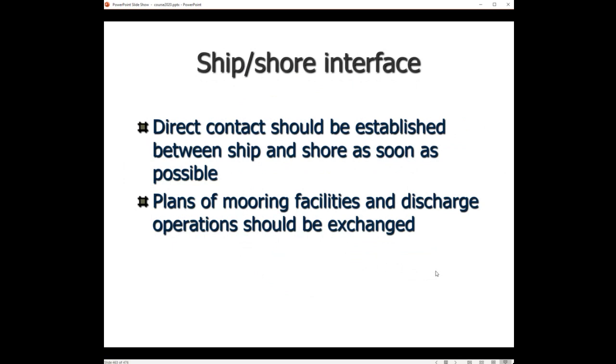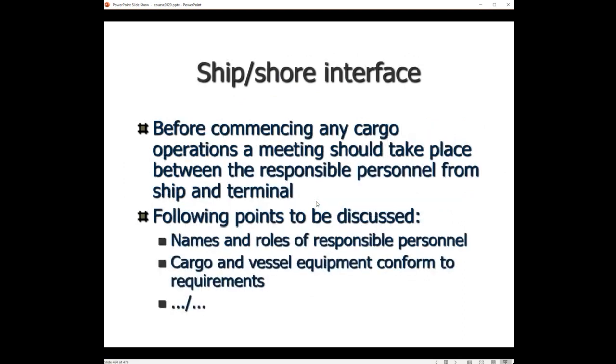What to do in emergencies, how the quick release can be operated, who will operate that, and who will activate it, and so on and so on. Names and roles of the responsible personnel, who is responsible for the operation on board, who is responsible for the operation at the terminal.